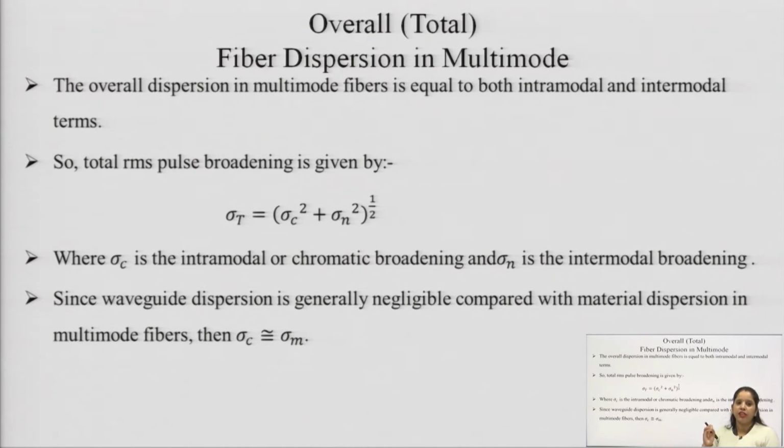So, whatever be the pulse, the exact pulse width at the input section does not remain the same at the receiver input; it gets broadened. Due to this broadening process, our adjacent, that is neighboring, pulses overlap with each other, and we face the problem of intersymbol interference, which is represented as ISI.